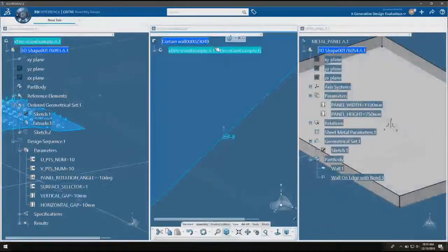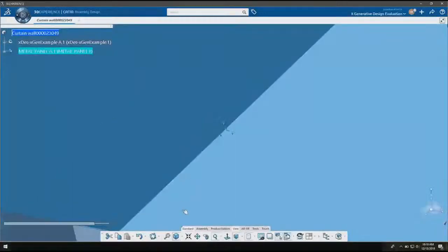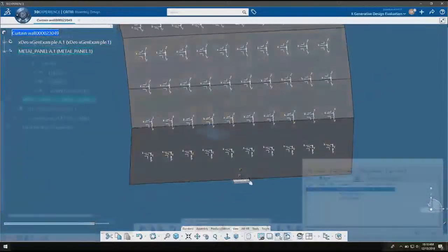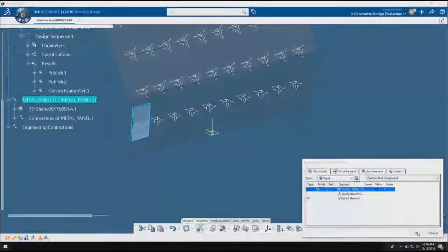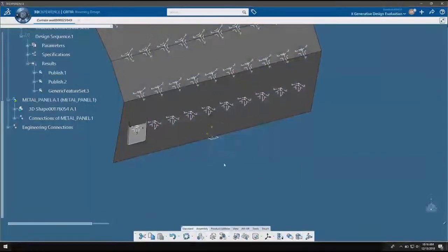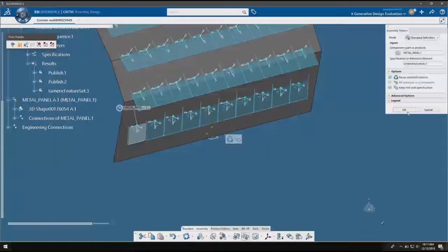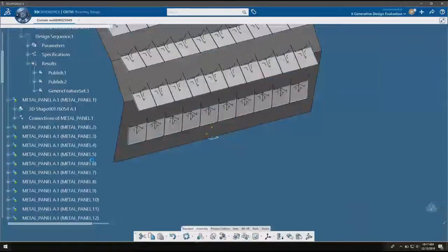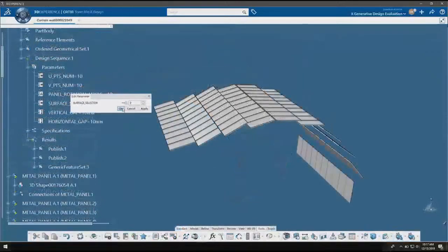And now I'm going to create a CATIA assembly, a curtain wall assembly. So I'll input my X design and X generative design model. I'll input my sheet metal panel, and I assigned the width of this sheet metal panel based on the rectangle sizes from X generative design. I can do an assembly constraint to position my sheet metal panel in place, and do an assembly pattern to replicate that panel across all of the axis systems in my model.